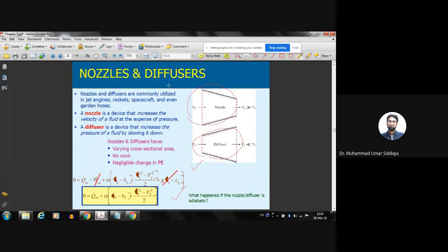Am I right? This is your question. Yes, you're right. It's because we are also not wrong there. But let me tell you how it is. Look, the water is coming out and the outside pressure is atmospheric, so definitely the pressure of the water at the time it is coming out of the nozzle is atmospheric pressure. That cannot change. The only thing is that when we say the pressure is very high, it's because of the back pressure at the inlet of the nozzle.